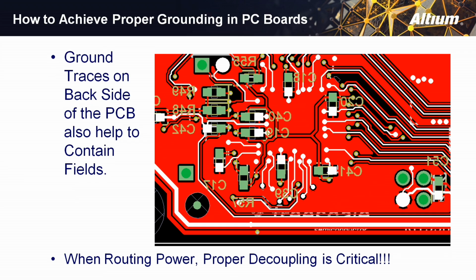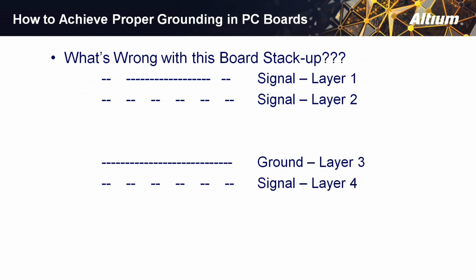Notice that they routed power in this particular board, and I hate to tell you, but they did not do a good job of that either. They left the decoupling where it was. Maybe sometime in the future we can do a presentation on proper power delivery, because believe me, these guys did not do that very well, but that's fodder for another discussion.